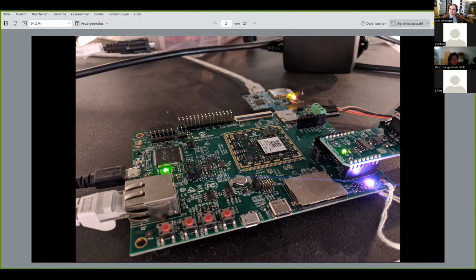And there are also hooks of LabGrid into upper layers going into Python for PyTest, for example, so that in the session scope, you can put your bring-up portions like switching on boards, waiting for it to boot into a special mode. Let's say you're waiting until Linux has been booted, and then you can actually execute tests. Yeah, so that's why they built it, right?